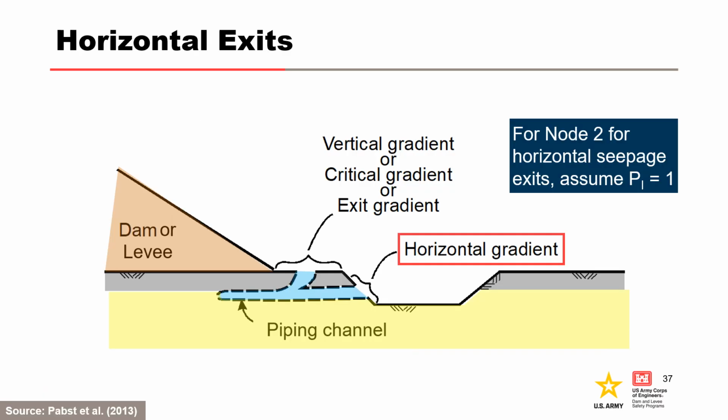In this figure, backward erosion piping channel formation is shown with initiation at 2 potential locations near the embankment toe for illustrative purposes. Both would not form simultaneously. Upward vertical hydraulic gradients are resisted by gravity and relate to the potential for heave or blowout and the possible initiation of backward erosion piping.